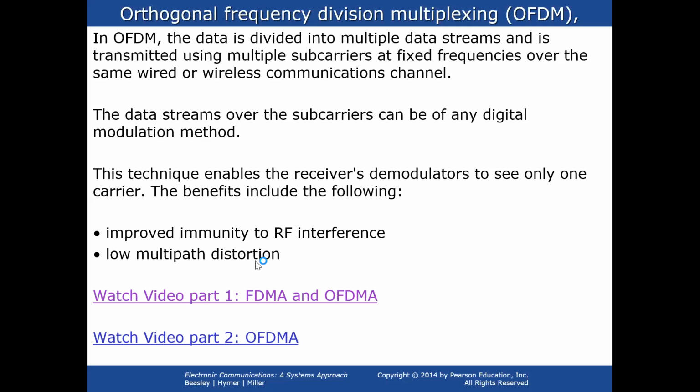This in turn negates the use of guard bands. As a result, the subcarriers can be closely packed to increase channel efficiency. Now, before looking at the multiple access part, let's understand how OFDM, or orthogonal frequency division multiplexing, works, and how it's used in long-term evolution.